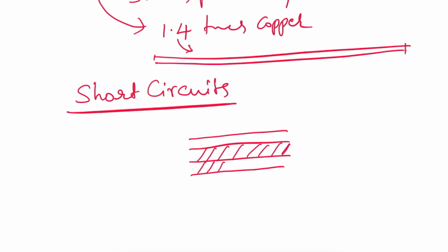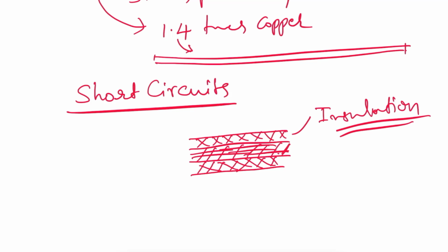So this is insulation, and then above that sheets, jackets, etc. will be there. The central one is of course conductor, you can see. So surrounding the conductor there is insulation. What is its maximum tolerable temperature? And surrounding this again you have sheet, jacket, etc. On these, how much temperature they can tolerate. Based on that, the short circuit considerations have to be taken into account. The size of the conductor, etc. has to be designed accordingly.